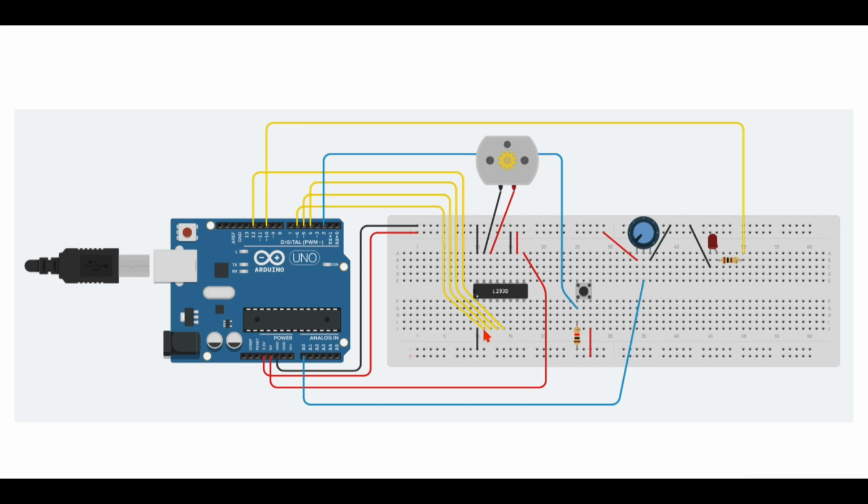This first one here determines the speed, and it is using pulse width modulation, or PWM for short. So it will simulate a higher or lower current with flashing a singular current on and off at an interval. And however much this is how fast the motor will go.